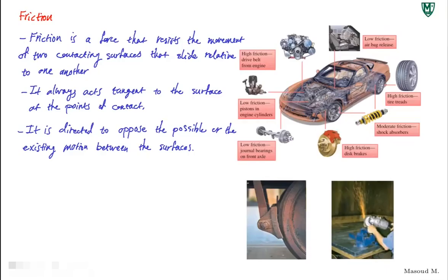If the friction is low between the shaft and the belt, the shaft keeps rotating while the belt is not moving, which is not something you want. For every turn you have in this shaft, you want that power to be transferred to the other shaft through this belt. So you want a lot of friction there. So it really depends on what the purpose is. If you're sanding a surface, right, you're trying to flatten some surface or make it smoother, you want friction there. You want friction to take particles off that surface. So that's another place where you actually want friction.